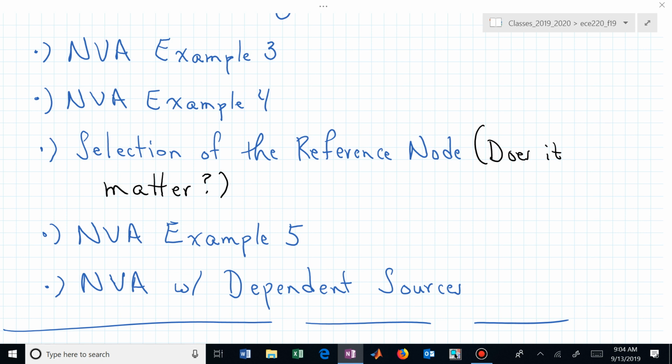You'll be able to say, oh, this element is absorbing this much power. Well, maybe your V's are not the same as someone else's, but they should get exactly the same amount of power being absorbed with that element. The results should be consistent, even though the voltages, as you have them labeled, may be completely different.